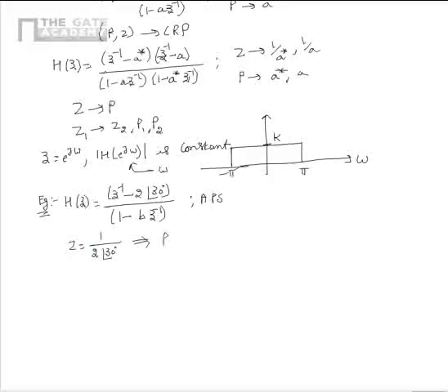So that implies the pole is located at p, that is equal to 1 by z star, which would be equal to 2 phase minus 30 degrees. From this, we see that in case of an all pass system, poles and zeros form conjugate reciprocal pairs. So the value of b from this is equal to 2 phase minus 30 degrees.